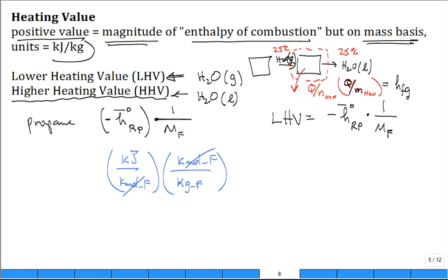That makes sense? And so now you think about, here was the combustion, you had the reactants going to products. The rest of the products just go for the ride, but the one product of interest is water condensing. So you have the lower heating value, added with this additional heat transfer to make the higher heating value. So the equation to compute the higher heating value is going to be the lower heating value plus, look at the units on it, how many kilograms of fuel, true?